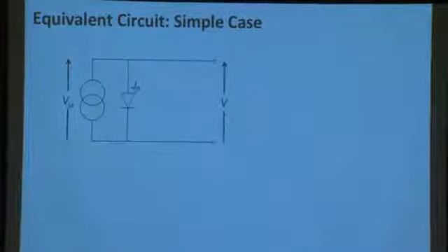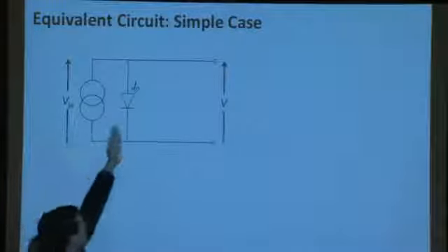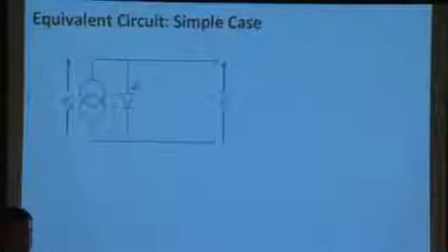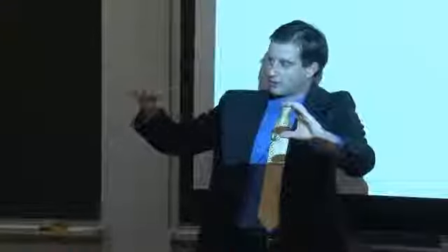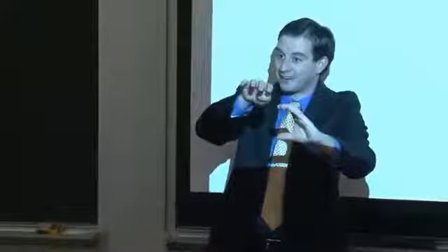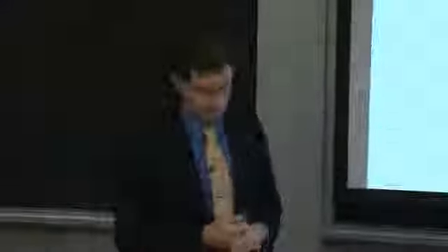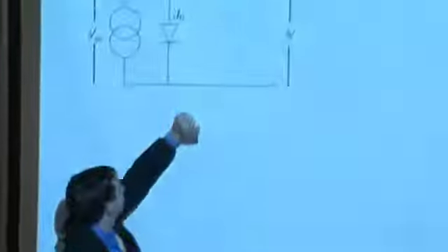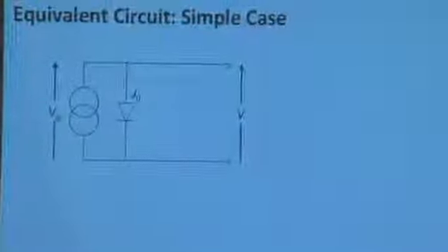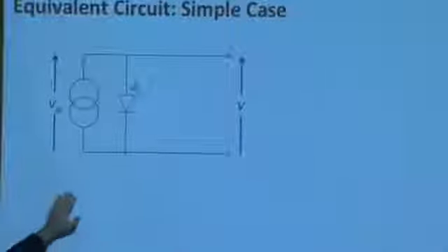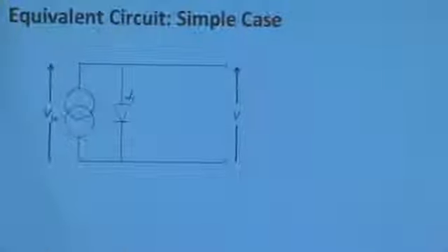If the diode quality is poor, you will have so-called leakage current leaking into the diode back, if you want to think about it in the forward bias conditions. Here's your solar cell forward bias. You have electrons coming in, separated by the electric field. Instead of powering the external load and coming back into the device through the back, leakage current would be the electrons going back up the barrier, right? Going back into the base of the device, the so-called diffusion current. So this is that diode right here representing the diffusion current, or in that particular case, in the ideal equivalent circuit diagram, this is representing the resistance to diffusion, if you will.